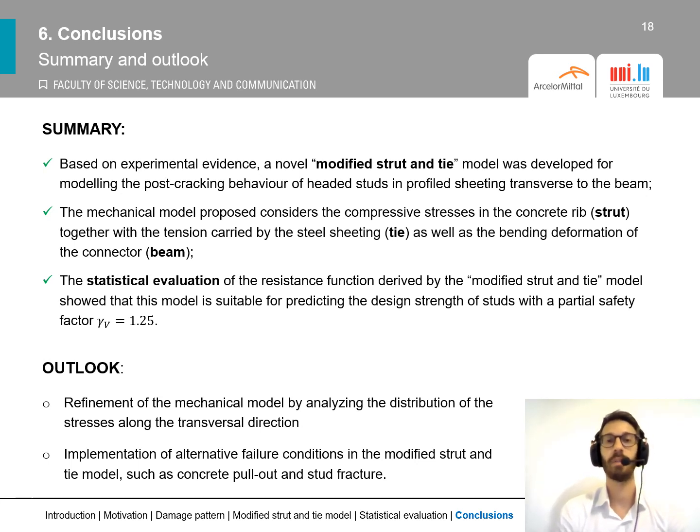Finally, the suitability of the resistance function derived by this model was checked by carrying out a statistical evaluation, which showed that this formulation is suitable for predicting the design strength of studs with a partial safety factor of 1.25. Nonetheless, there are still some refinements that can be considered. For example, analyzing the distribution of the stresses along the transversal direction, as well as implementing alternative failure conditions within the model, such as concrete pull-out failure and stud fracture.